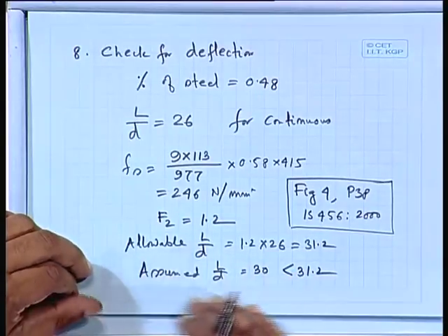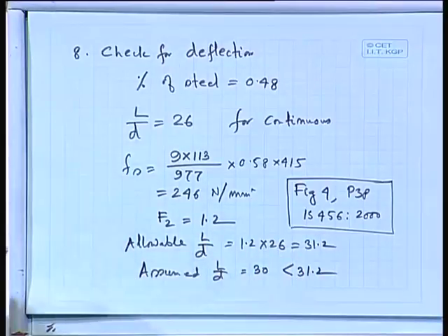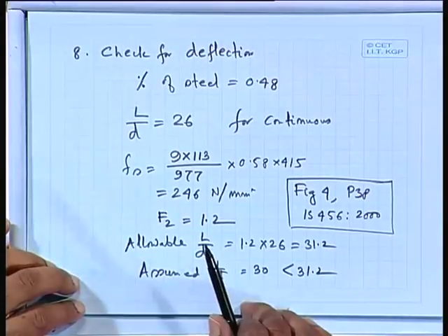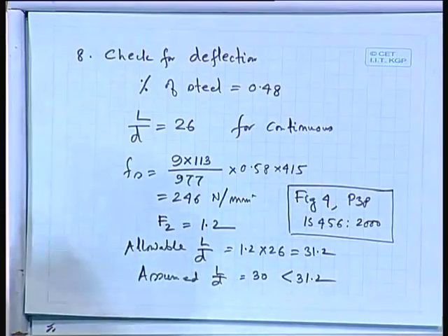Okay. So, one more checking is there, and that is related to your crack. There are two things, these are coming from serviceability limit state. One checking is coming from the L by D ratio, and other checking will come from the spacing. So, you have to check the spacing whether it is less than 3D or not, and obviously whatever we have provided, say 9 bars in 1500 millimeter, you will find out that is less than 3D.